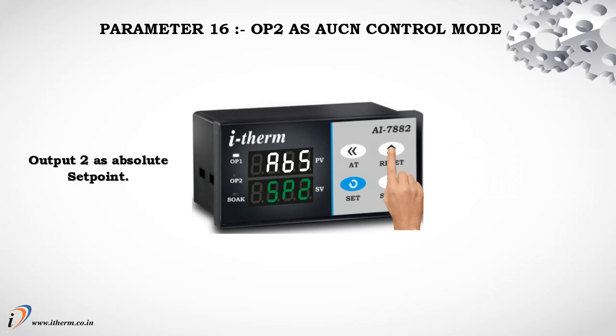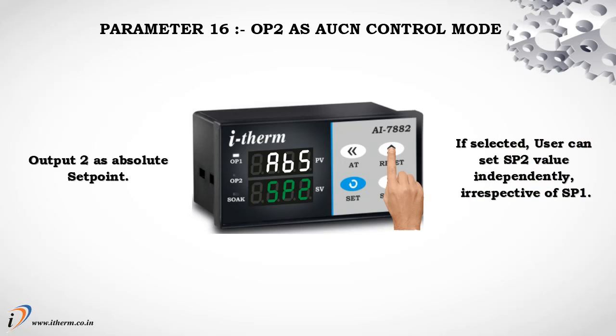Parameter 16, Output 2 as auxiliary control mode. Output 2 as absolute set point. If selected, the user can set the setpoint 2 value independently, irrespective of setpoint 1.